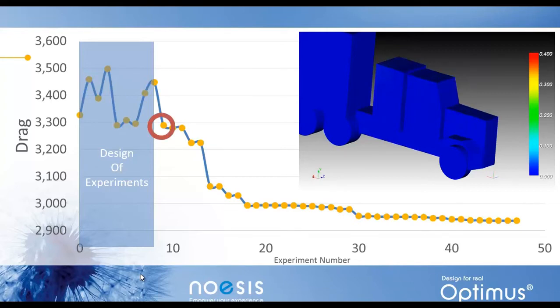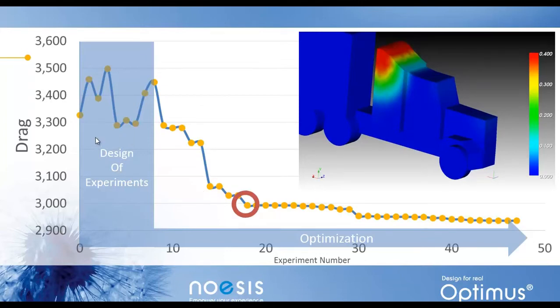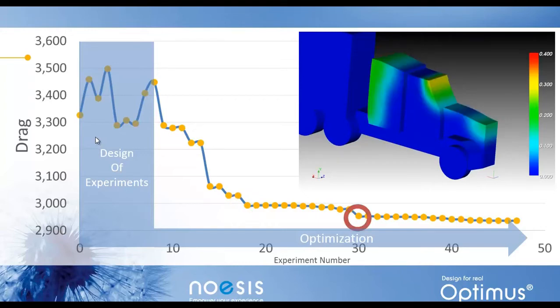And then it hands off this DOE automatically to an optimization algorithm which progresses to further reduce the drag coefficient and find the best values. So that's just a very simple way of visualizing optimization: the software helps you by automating this and by focusing only on the feasible and optimal zones. You notice that you're not getting a lot of sampling outside of the previous best design.